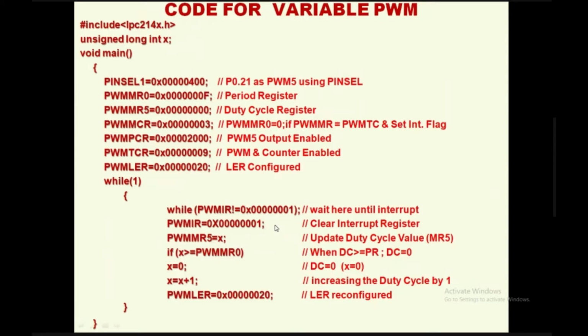Okay, that is what we have made it in the GPU itself. In the set register and the clear register, we made it 1 to clear the bits. Similarly, for all ARM processes, whenever you want to clear something, you have to make it 1. So to clear the interrupt register, the bit has to be set as 1. That is why the PWM interrupt register is 1. So now it was cleared.